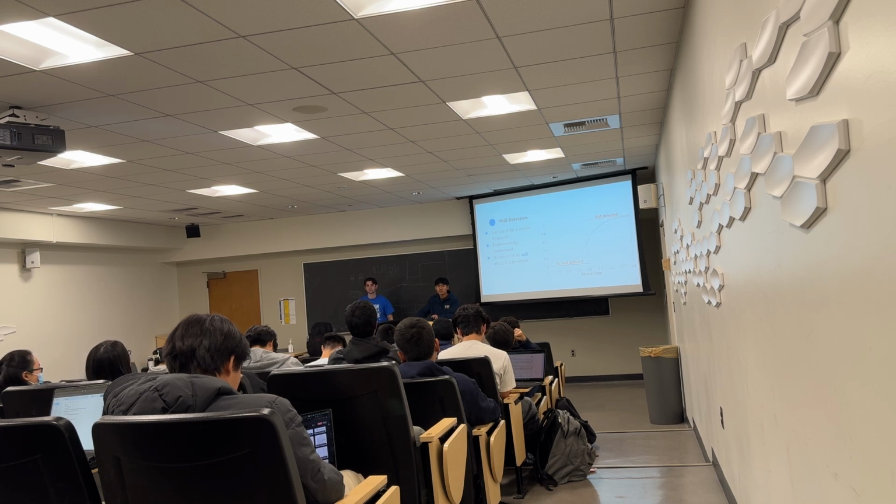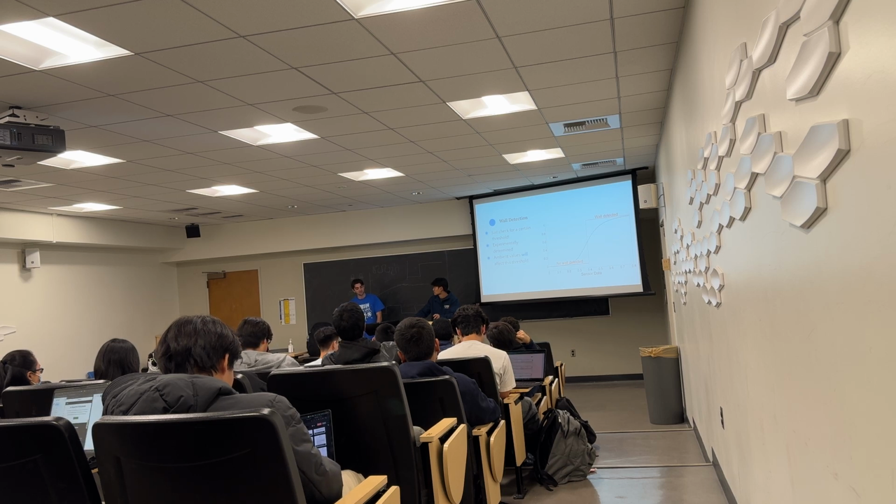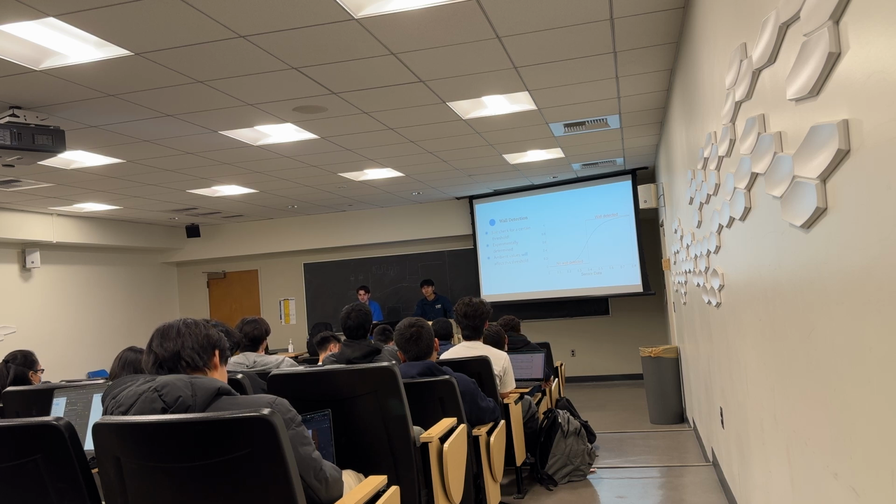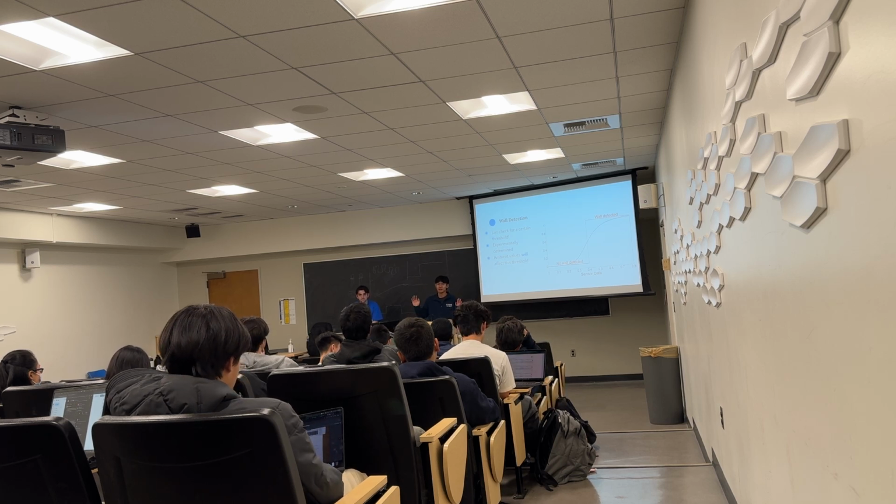Do you have to recalibrate every time? You might have to. I didn't really have to last year, but it could depend on the ambient light in the room. I finished at night, and the competition room had pretty much no sunlight, so the IR values were pretty much the same. But yes, you could have to recalibrate, though it shouldn't be too hard. I also think during competition they'll give you time to set up your calibrations.